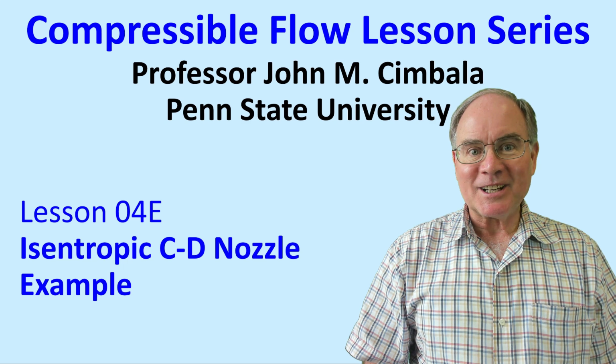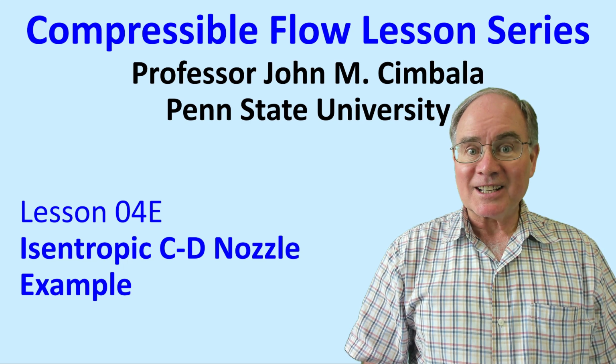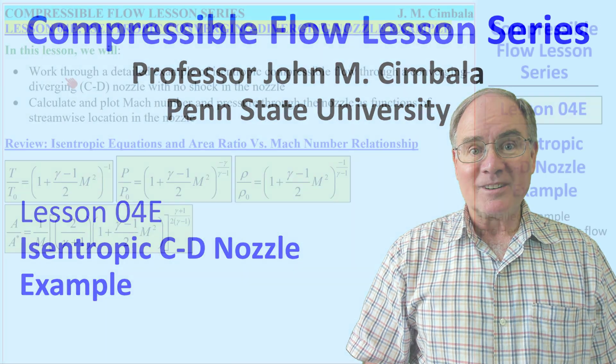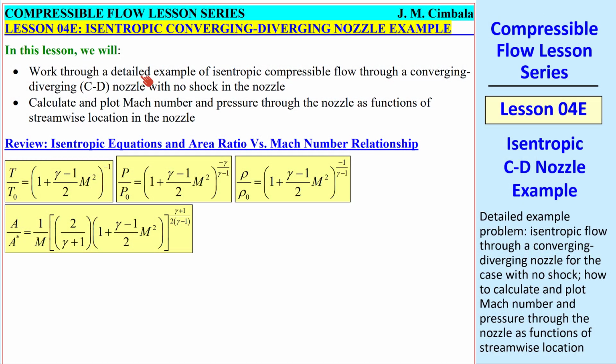Welcome to Lesson 4E, Isentropic Converging-Diverging Nozzle Example. In this lesson, we'll work through a detailed example of isentropic compressible flow through a CD nozzle when the back pressure is low enough that there's no shock in the nozzle. And we'll calculate and plot Mach number and pressure throughout the nozzle and compare our theoretical results with those calculated